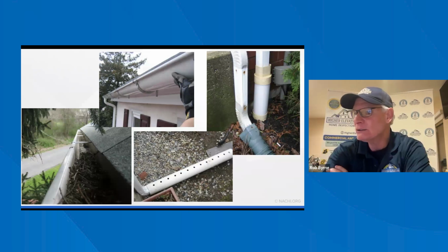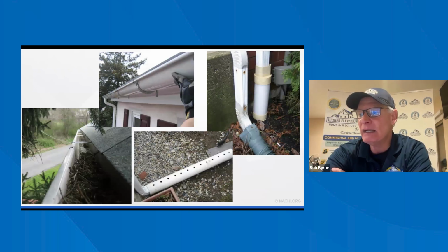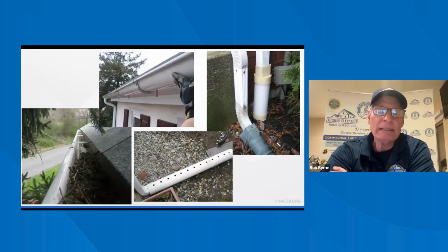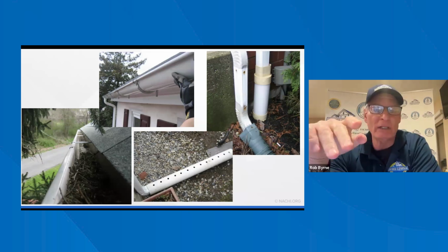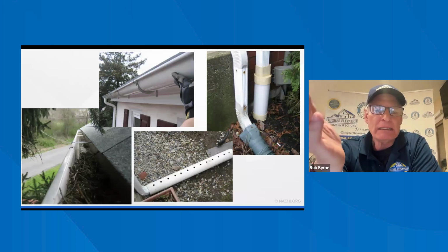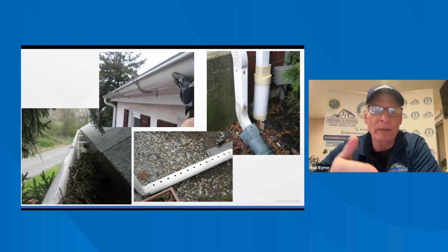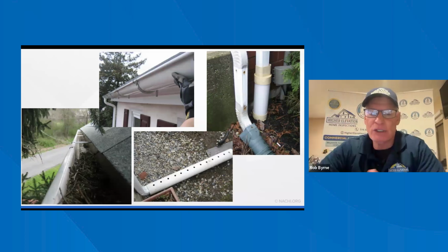So what do we got here? Storm drain basics. Gutters and downspouts or other means should prevent rainwater from washing soil away from the dwelling foundation or building up around and increasing groundwater pressure on the basement walls. Talking about hydrostatic pressure here. The size of a drainage pipe should not be reduced in the direction of flow. So what they're saying here is, a lot of times you'll go to a house, and number one, if they don't have gutters, we call that out. And you can see, if you don't have gutters, you look directly below the edge of the roof, you'll see it's channeled out.